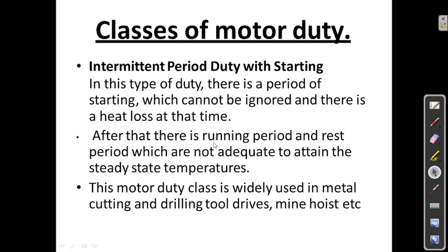Then intermediate duty with starting. In this type of duty, there is a period of starting which cannot be ignored, because of the heat losses at that time. After that, there is a running period and a rest period which are not adequate to attain the steady state temperatures. This motor duty class is widely used in metal cutting and drilling tool drives, mine hoists, etc.